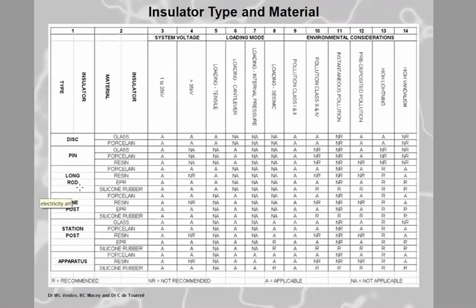Long rods can be made from porcelain and resin and ethylene. EPRs is the EPR rubbers, which is actually more EPDM, ethylene propylene diene monomers. Okay, they've got a tertiary carbon atom, very prone to UV. The UV will split the tertiary carbon atom, one shot, boom, and the chain breaks. And as it breaks, it cracks.